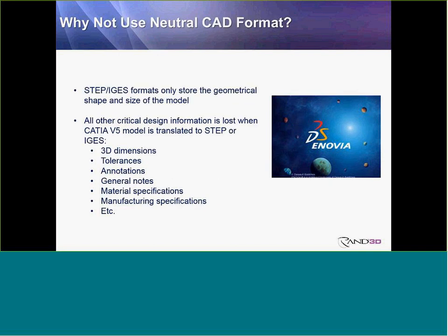Neutral CAD format. So you might say, okay, what if I ask my OEM to simply export the model into IGES or STEP and go from there? Well, STEP and IGES only store the geometrical shape and size of the model, and all other critical design information is lost during translation.